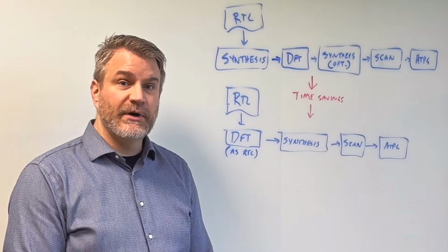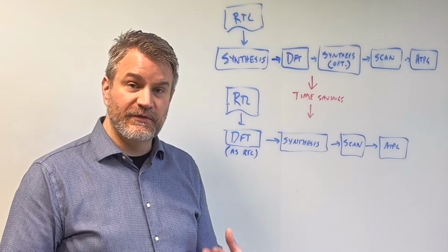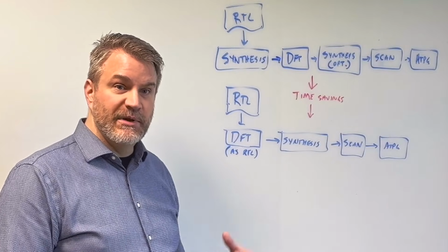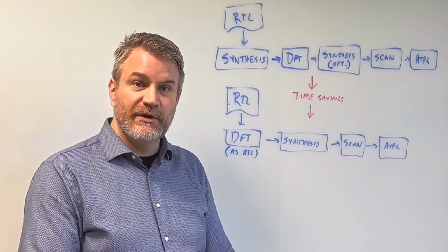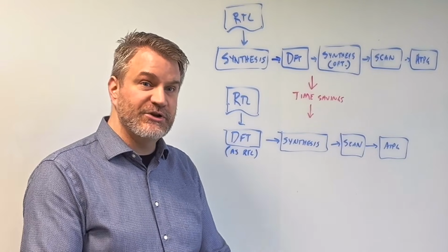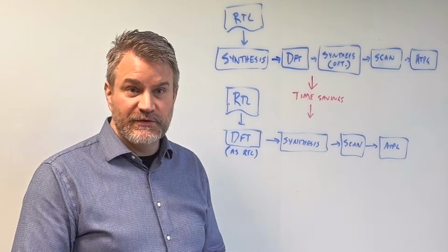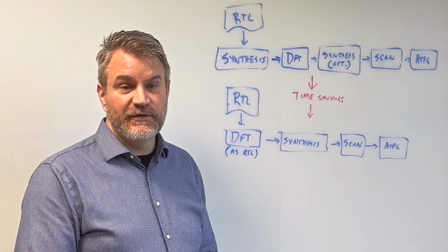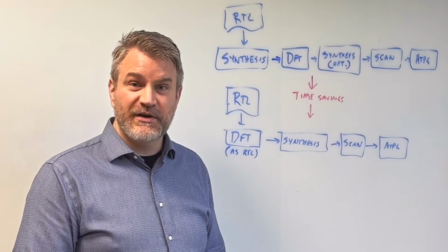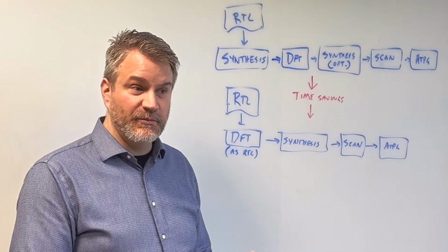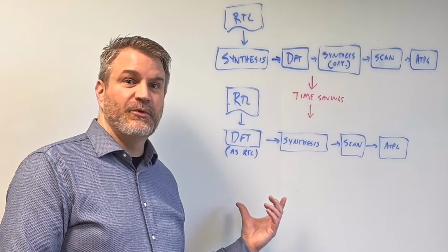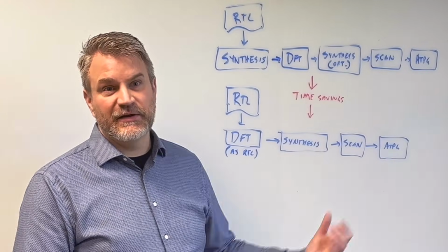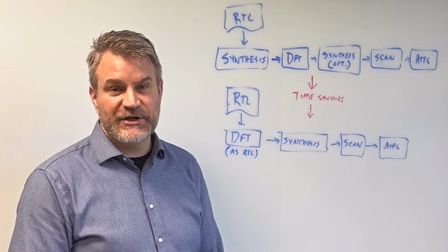Right. And that's where test points at RTL are helpful, especially with your last question. As the design changes, a lot of the controllability structures may change, because with 2.5D and 3D circuits they may not be accessible. We need to add test points into the design to improve logic BIST test coverage, to make the designs more testable. And so adding the test points at RTL is the best way as the designs change, so that all of the DFT logic can continue to adapt to the design as it changes.